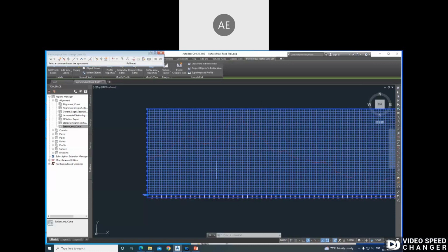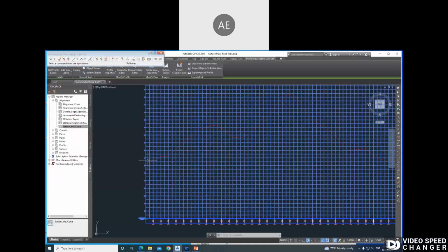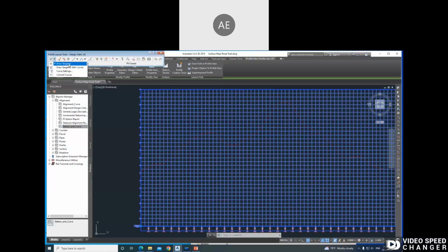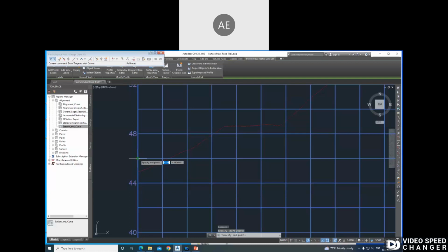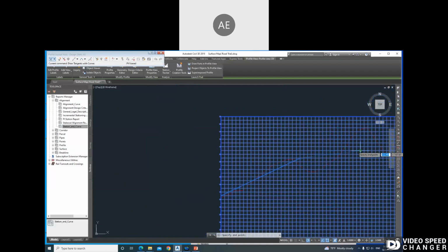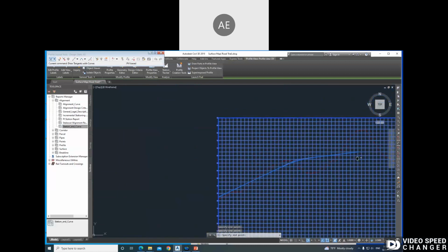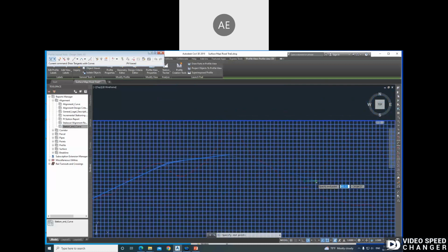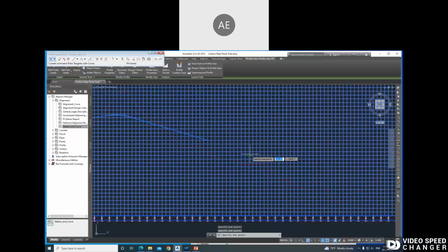As we did when we drew the alignment, now we have to draw the vertical curve. The same scenario, we have tangents only, or tangent with curve settings. I'm going to choose the tangent with curves. We will start, let's say, here, at this point, and we will increase in this direction here. Okay, later on you see the curve now. This is the transition curve, in this direction. Okay. I know, maybe I'm exaggerating, but here it's just to show you how to draw. It is not an actual study, just to show you the cut and fill later on.